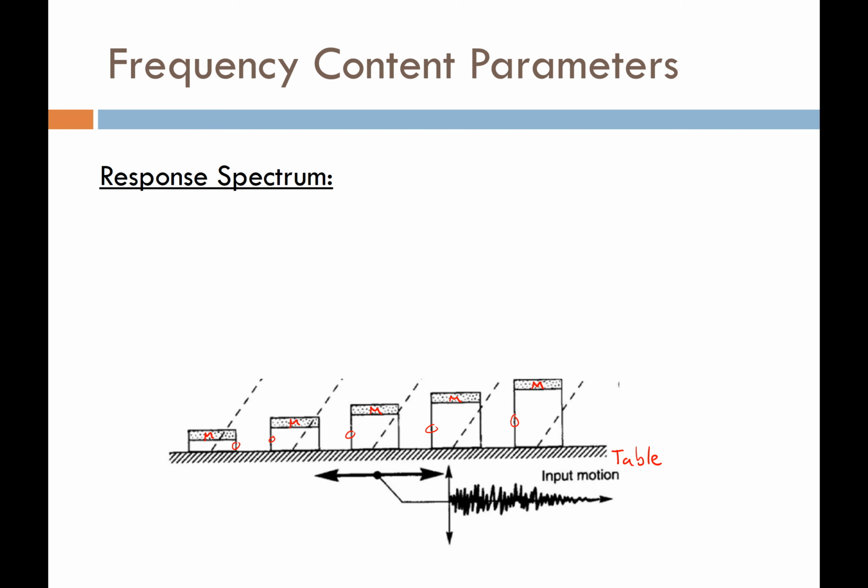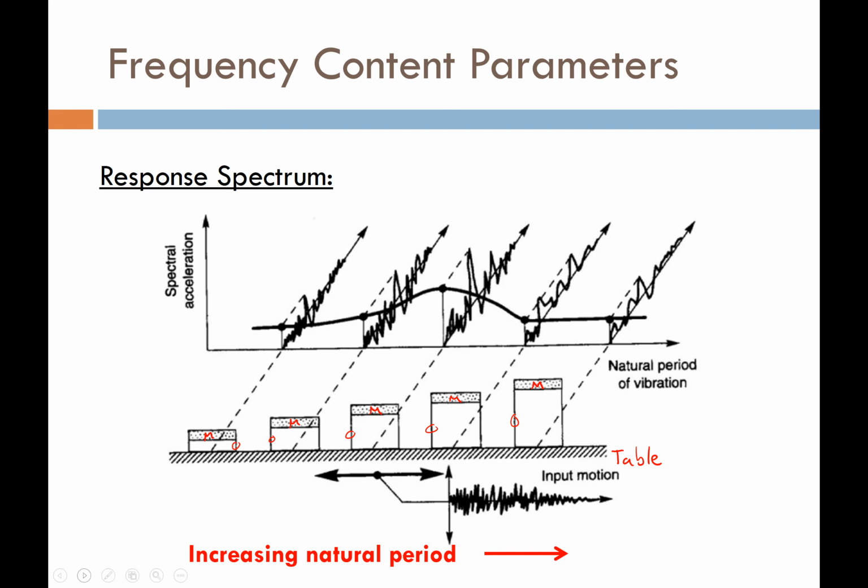And so if I shake the table on which all of these buildings are attached, they're each going to rock according to a different frequency. Now, if I go ahead and plot the response of each of these masses as I introduce each one to the same input ground motion, I plot that response of that mass, and I take the peak response,